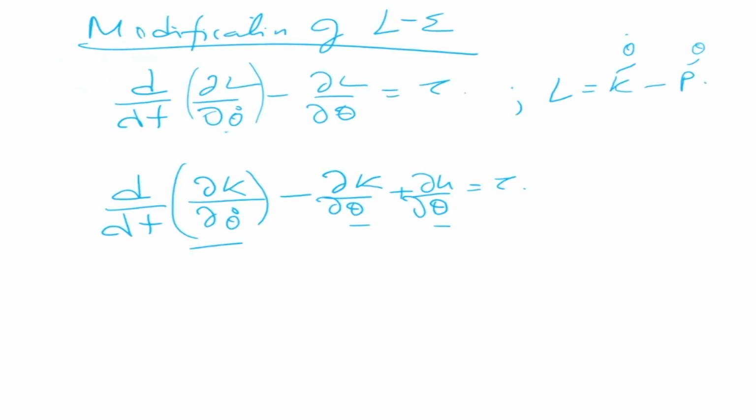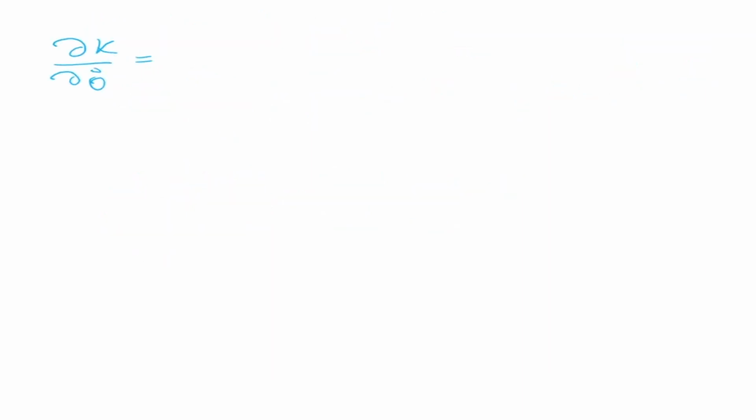So we have completed the potential energy and the kinetic energy. Now I find my dK/d theta dot. I actually take this equation one by one. I'll first take this term, then this term, then this term, then I'll take d/dt of that term. So dK/d theta dot is equal to, remember that this one has a theta 1 and it has a d2 dot and it has theta 1 dot.